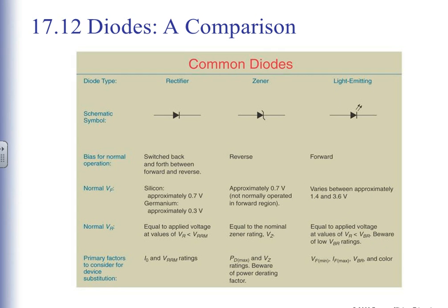And that's why when I test the diode to see which lead it is, I touch it to the 5-volt power supply and I take it off right away. Because if I left it there and I was wrong, it would burn out. Maybe I ought to try that. No, I don't think so.